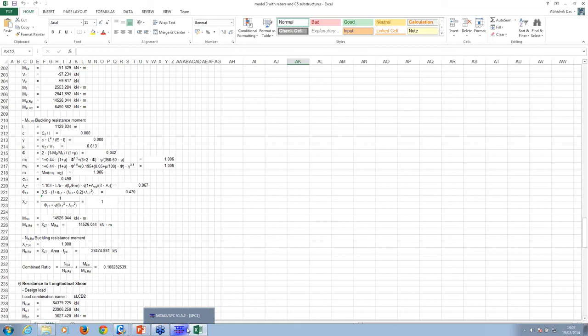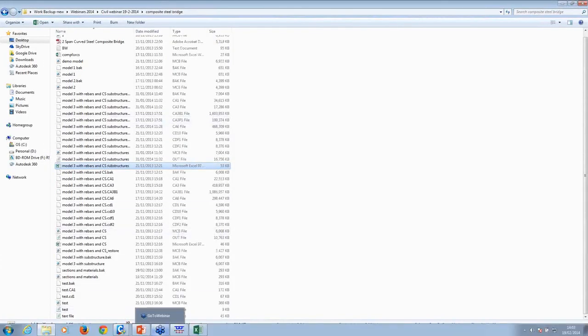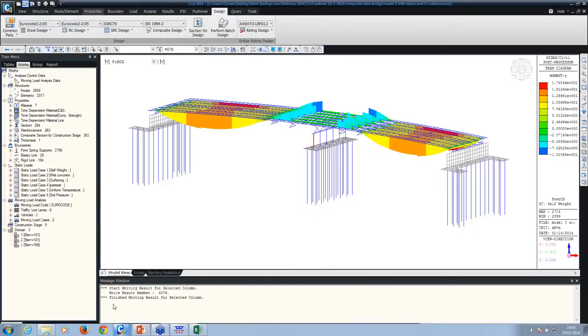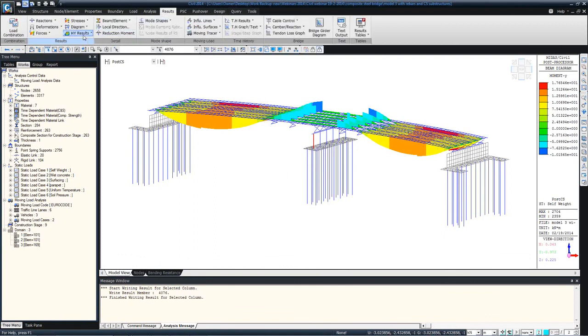Okay, there is another question. Can you show the beam and plate results at the same time? Because these are two different types of elements, beam forces and plate forces are displayed separately. Beam forces and truss forces can be displayed at the same time because they are both line elements. But for the shell elements, you have to see it through the plate force diagrams. So that's where you see the plate forces, and you can also sum up the plate forces to get the equivalent beam force.